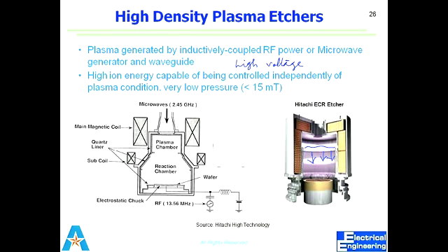So what we do in deep reactive ion etching is that there are cycles of passivation layer deposition and etching process. So you etch, you deposit passivation layer. You etch, you deposit passivation layer. In that case, the process is still isotropic. But in the first cycle, I did this thing. After that, I deposit the passivation layer. So that passivation layer, first of all, is deposited. After that, this passivation layer can be removed only from the bottom.